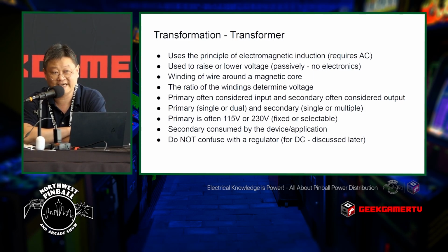Again, if you take a transformer that's configured for 110 and you bring it to Europe and you shoot 230 through it, you'll get double the output. So what would come out as 50 volts in the US comes out as 100 volts in Europe. And that will probably fry a lot of things very quickly.